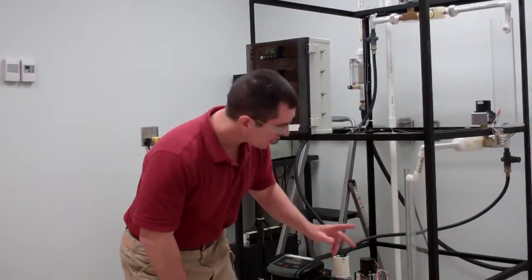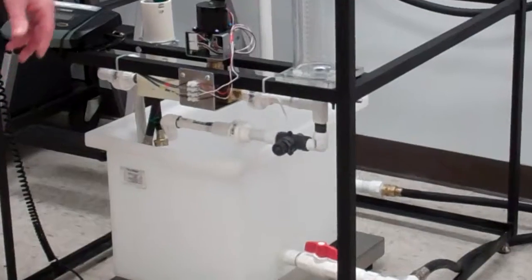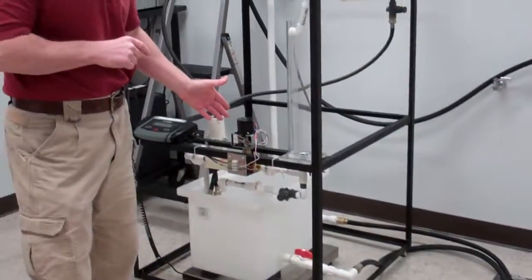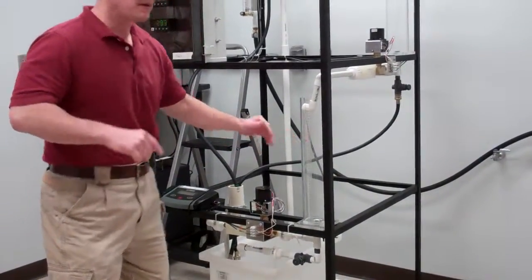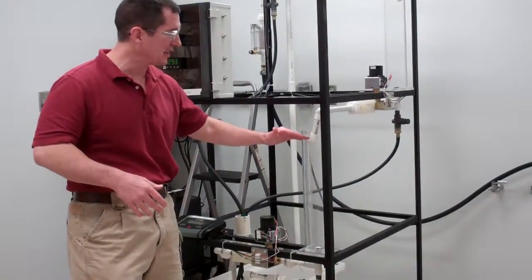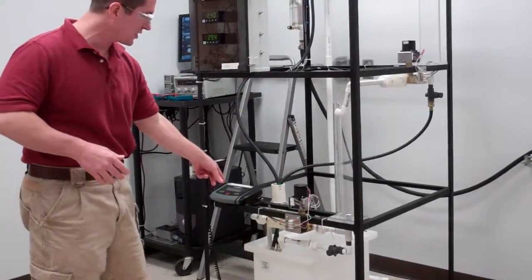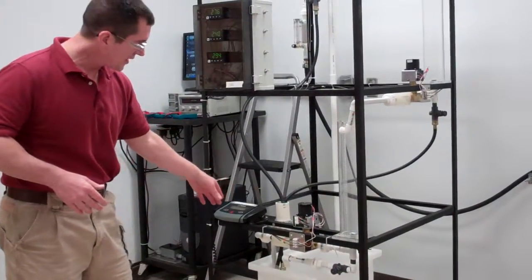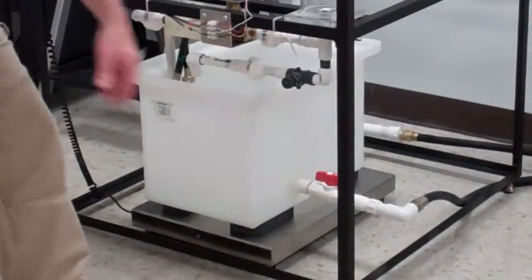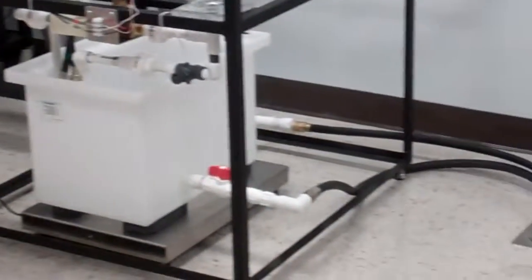You'll also notice that on the bottom of each one of these tanks is a manual valve. Now these manual valves can serve 2 purposes. One can be used for an emergency drain, so if you're out of control on your system, you can't figure out how to get it back in control and your tank level is getting too high, you can open this valve and drain it into the main discharge tank, which is right here. And this main discharge tank actually sits on a scale as well and has a discharge valve that goes to a drain. So the purpose of that will be when you're actually measuring flow rates at steady state.